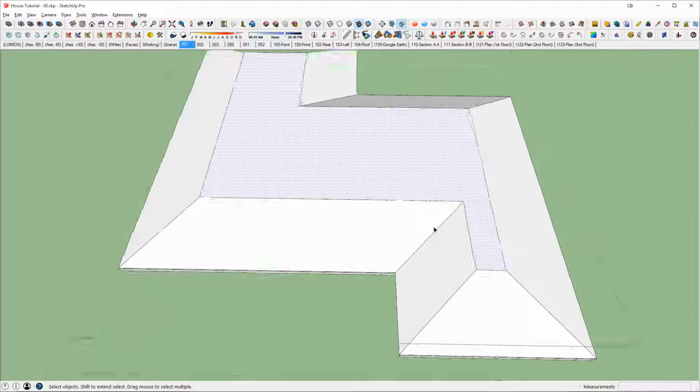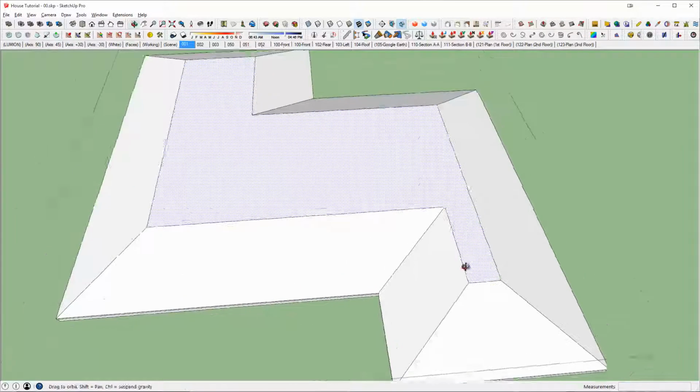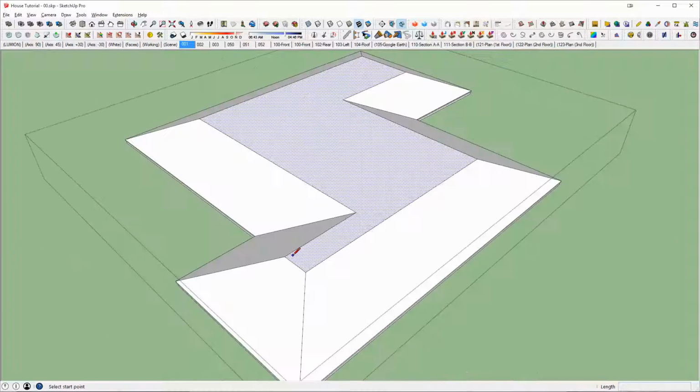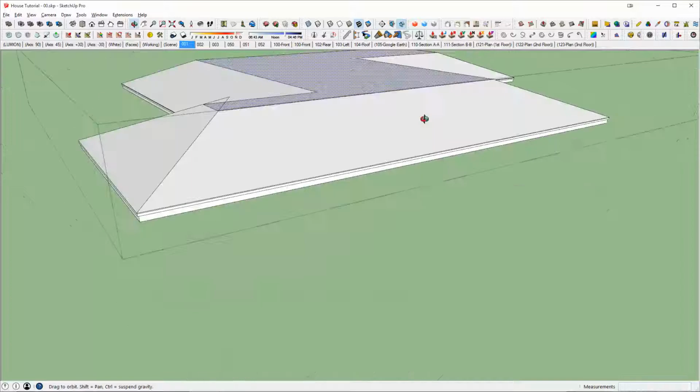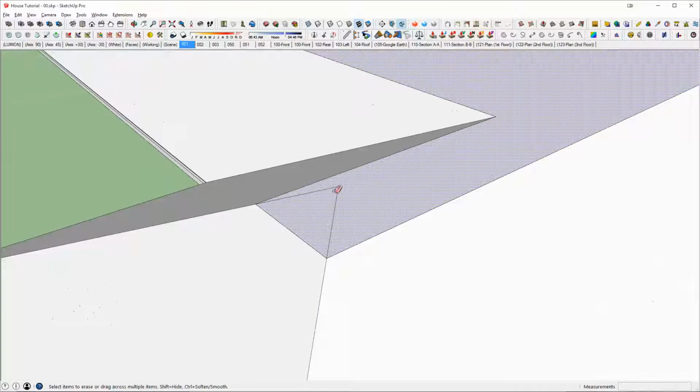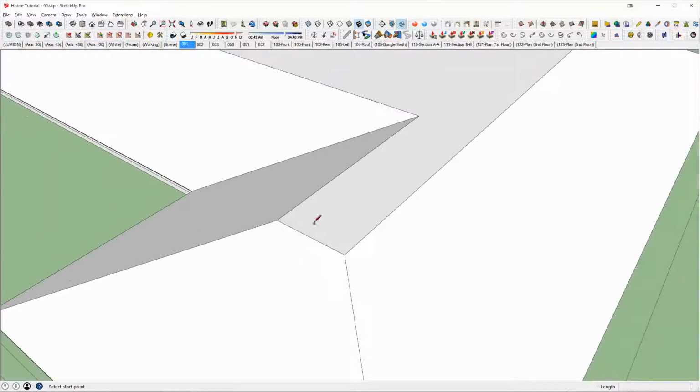And going back to our inference tools, you would see that to make this roof, or to finish making this roof, I can just hit the Shift key to lock myself on this edge, touch this face, and we're just going to quickly move around this model.